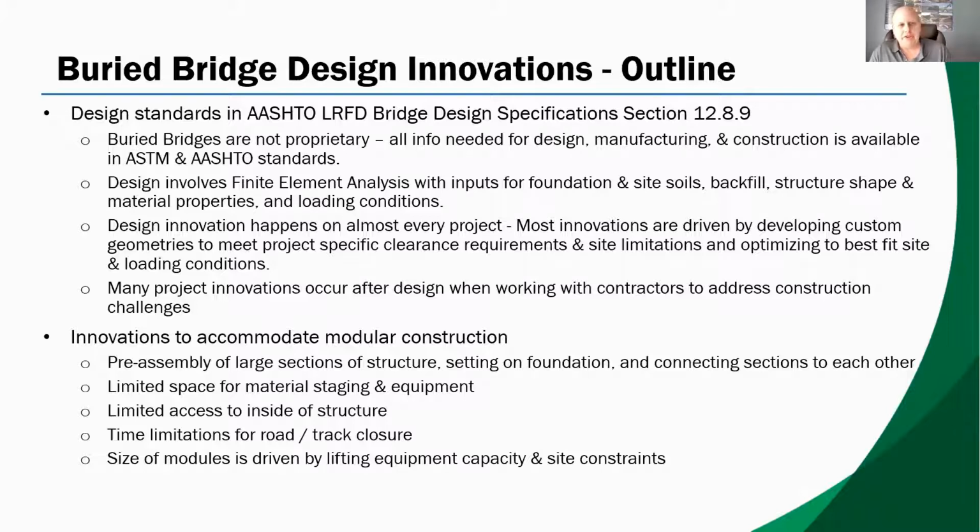There are a couple of different reasons that somebody might want to look at construction this way. One is that there's limited space for material and staging equipment. Usually when you're building these, you want a place to stage the plates so you can lift them in a convenient location to efficiently set them on the foundation and add them to the structure. A lot of sites just don't have the space for that, or the equipment that you need to build it, the site is too rough or on a slope or in a location you just can't get to.